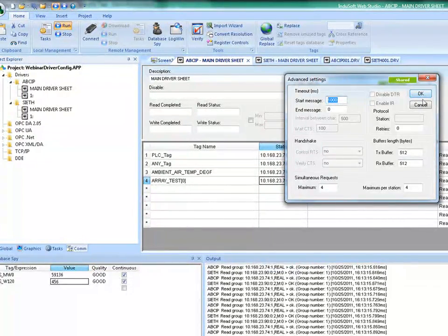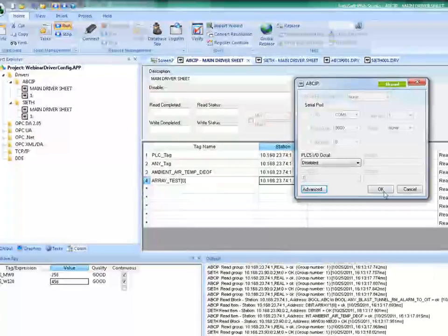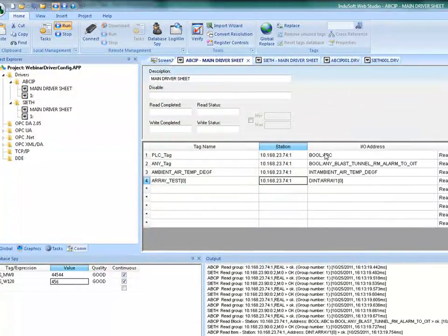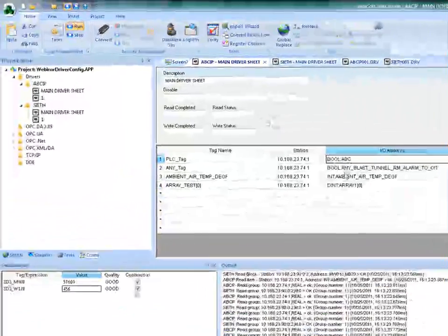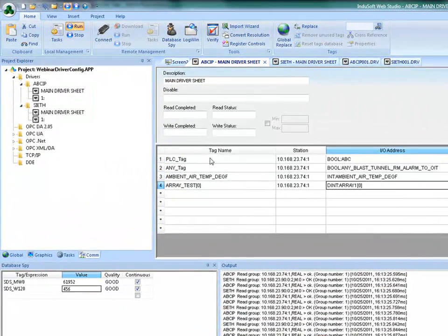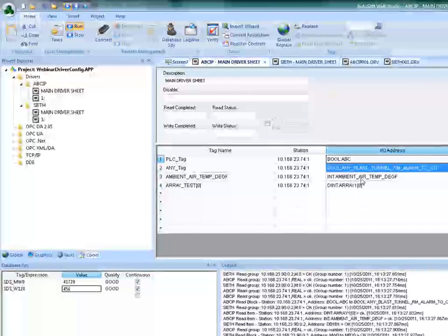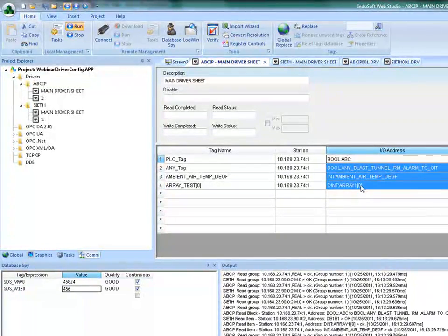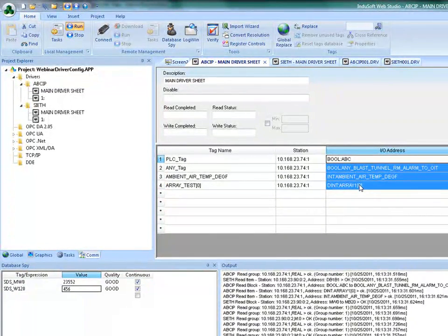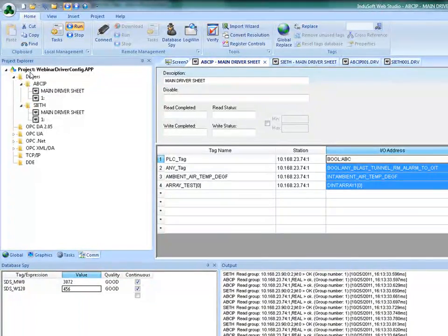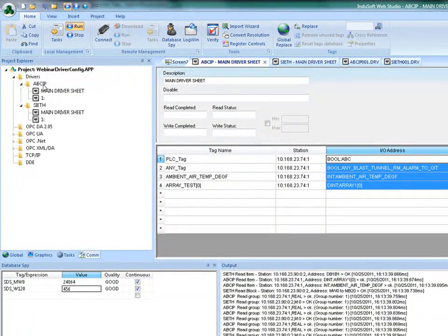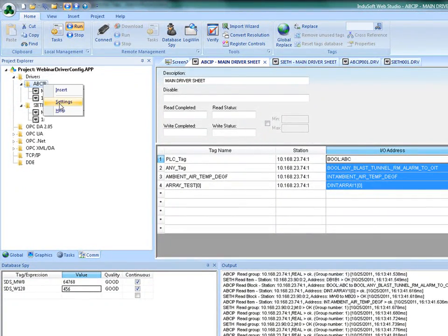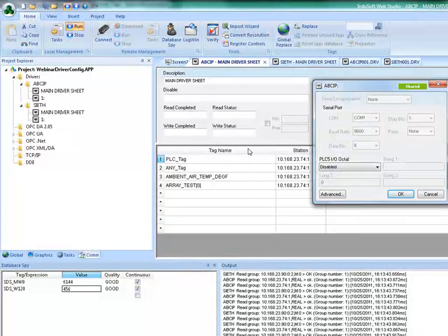Otherwise, we're going to be always communicating booleans first, integers, double integers, and then booleans, integers, double integers. If we open multiple connections, you're going to be talking to all of them at the same time. You're going to be sending a message to the PLC at the same time. Just keep in mind that each PLC has its own limitations of communications or connections. The Allen Bradleys, for example, are able to handle sometimes 60, I guess 64 connections.